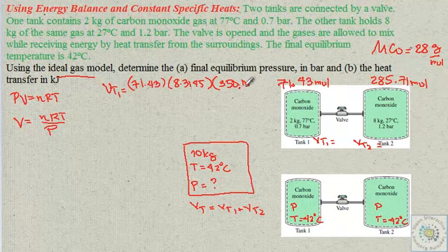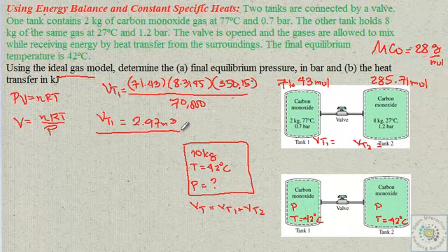So be sure to put things in Kelvin. And the pressure is 0.7 bar. That's 70,000 Pascal. Note, use standard SI units, so pressure must be in Pascal, temperature in Kelvin. And this will then lead us to a volume of tank 1 equal to 2.97 m cubed.